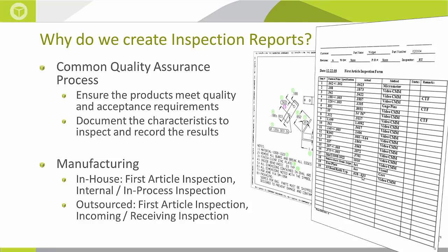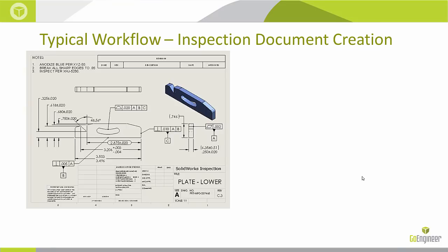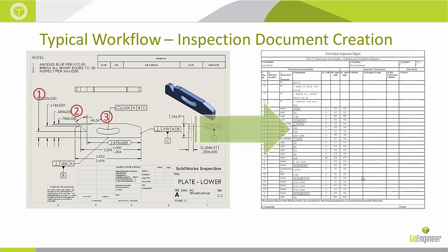And the typical workflow is you have a drawing from engineering, and once they have this drawing, some other functioning group, most likely a quality engineer, is going to take this drawing and balloon it. And when they go through the whole ballooning process, they're going to then take that information and put it on some type of form, whether it's an Excel document or Word document, something that someone can data log all of the measurements that they're going to be taking onto this part that they're measuring.